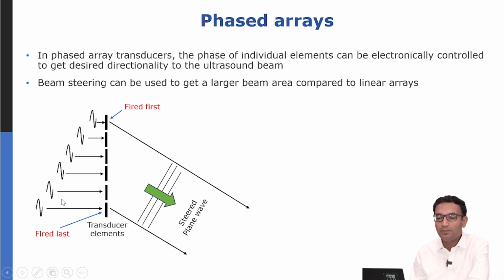So why would a delay profile cause this steering? Imagine you are doing march past on Independence Day with your friends. Now your group has to turn right, for example. How would you do that? The person who's marching rightmost would have to slow down, and the person who's in the same row but marching leftmost would have to speed up.